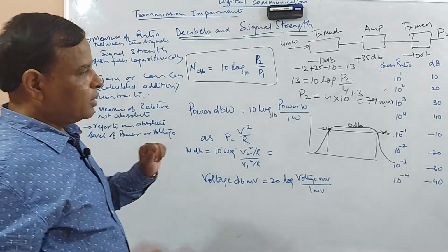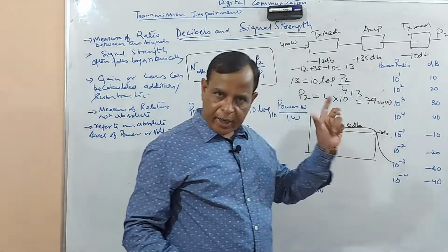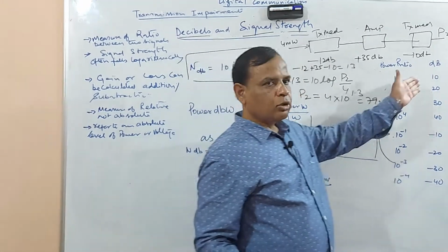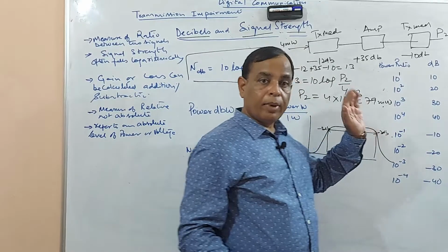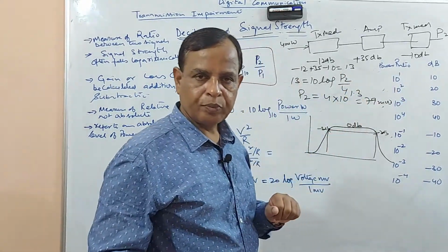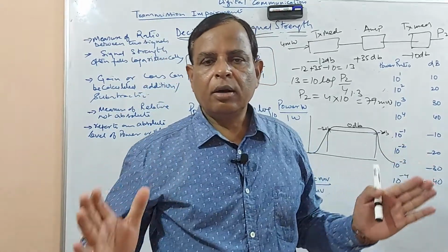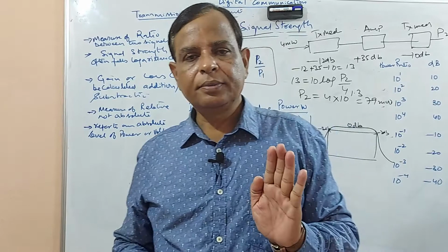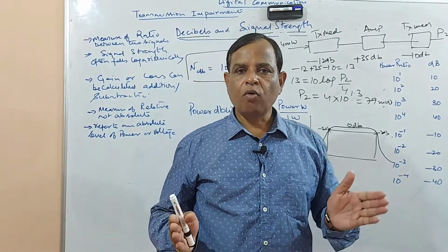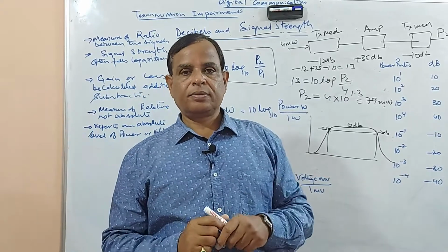Even the power ratios, so whenever you listen to this power ratio, the power ratio is 10, it is said to be 10 dB. Power ratio is 100, then it is 20 dB. Okay, so for example, if I am telling a gain, the amplifier gain is 30 dB. 30 dB means what? The gain is 30 dB means it amplifies 1000 times.